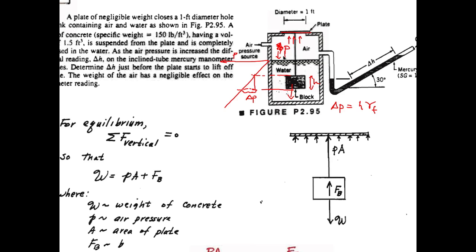If you increase the pressure in this tank so that it's acting on this surface as well as on this surface, then all you do is change this inclination here, but now this line is exactly parallel with the other one, and so the difference between the upper pressure and the lower pressure is again equal to delta P. And so what doesn't change is the magnitude of the pressure of the water acting top and bottom in either of these cases, and that basically says that this is the reason for buoyancy, and so the buoyancy doesn't change either. And so you can just use the buoyant weight. So I think that's the observation.